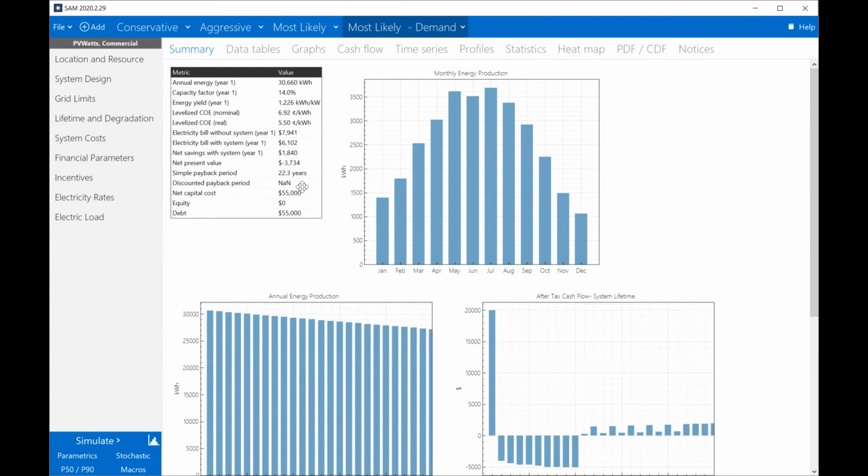And again, if you're going to model a demand project, I really encourage you to work with your utility and try to get your load profile data on 15-minute intervals, 30-minute intervals, 60-minute intervals, whatever their demand rates are based off of. So however they're calculating it, that's really how we need to input it.